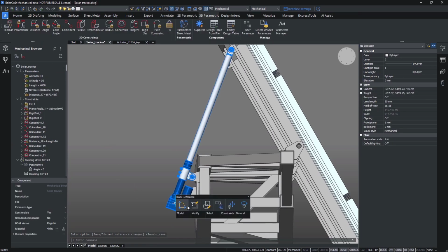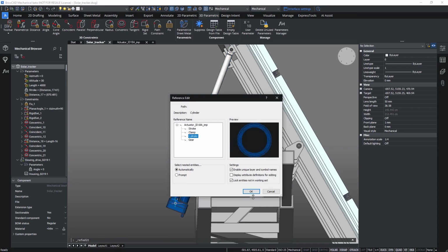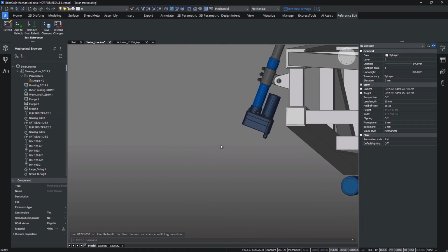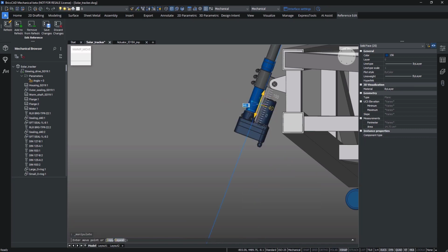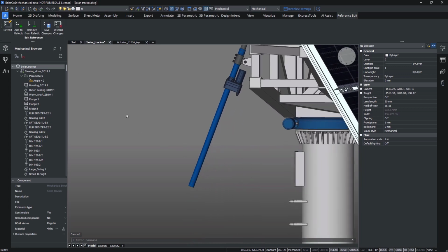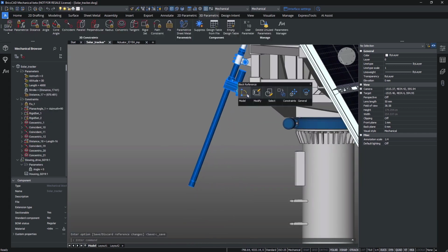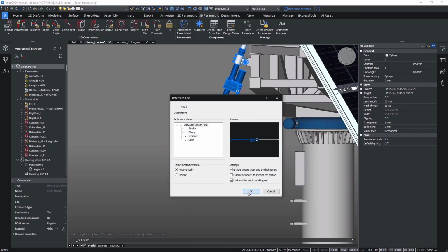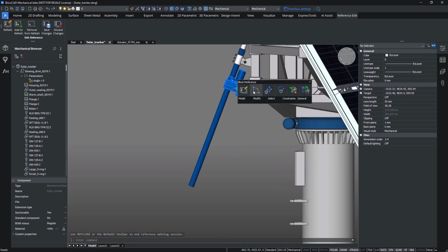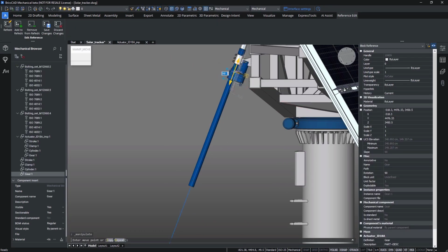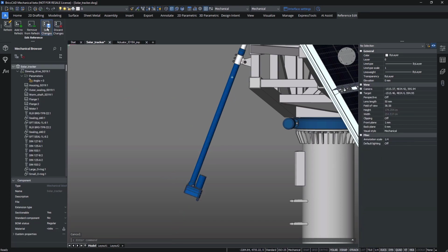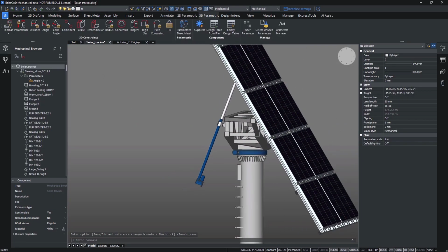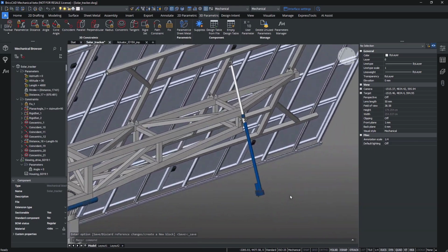As the stroke is now longer, the cylinder should get longer with the same extent. Let's repeat the same procedure. Select the contour and directly drag it to extend the extrusion. We should finally pull the gear component along the cylinder to the very end. At this point, the resizing work is finished. The imported actuator becomes usable on our assembly.